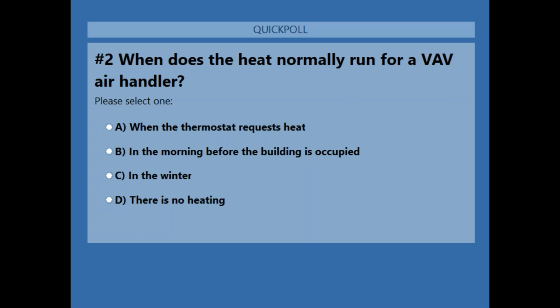All right, let's see if we have any questions for me while you guys are looking at that one. Chun asks, should one thermostat pair with one volume damper? The answer to that is yes. A normal scenario would be a 1-to-1 relationship between thermostats and dampers, because you're going to select the zones you want to uniquely control, so those guys are all going to get a thermostat, and then you're going to usually be smart about your duct work, so you can have one duct running to that zone, and hence one damper. So typically it's a 1-to-1 relationship of thermostats and dampers.